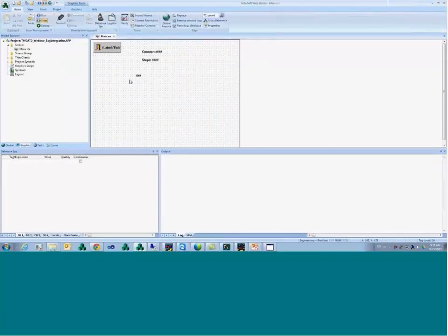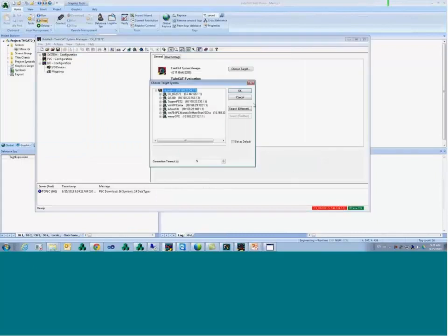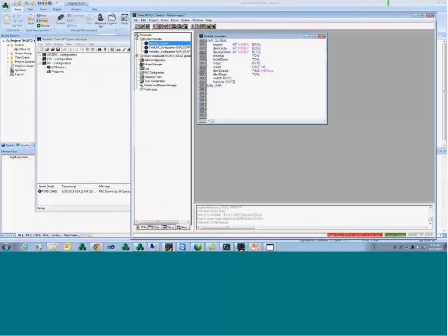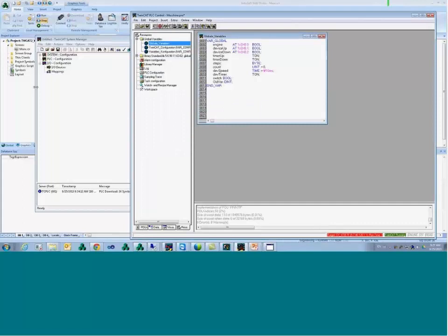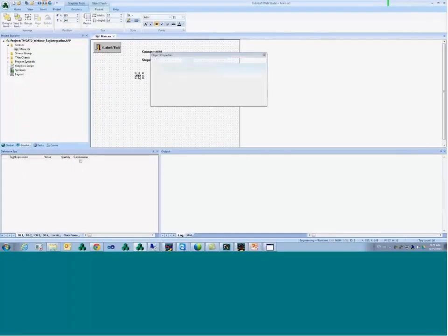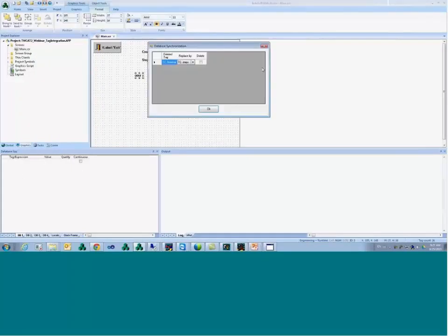I save it. Then, I'm going to go on my TwinCAT, and I'm going to change that variable name. Too much stuff open. So, instead of new var, now it became my old variable. Okay, I save, and I'm going to rebuild all. So that file has changed now. If I try to open here now, see, it shows that a variable was changed on TwinCAT.